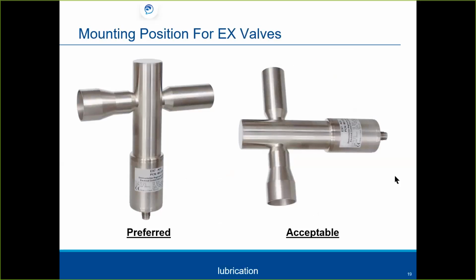This just shows the mounting position of an EX valve. This is preferred. This is acceptable. What wouldn't be acceptable is this motor on the very top. And this is typically when I would ask the students why that would be. And the answer is for lubrication for that motor, okay? We would never want that up on the top, vertically up. It should be down or to the side here where we can get some lubrication.